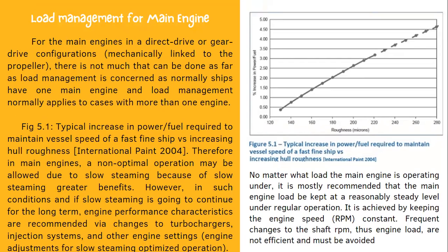I'm Engine Cadet Abejero and I'm going to continue with the topic. For load management of the main engine, in direct drive or gear drive configurations mechanically linked to the propeller, there is not much that can be done as far as load management is concerned, as normally ships have one main engine, and load management normally applies to cases with more than one engine.